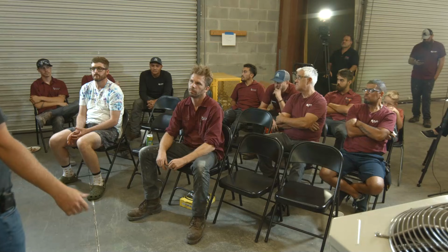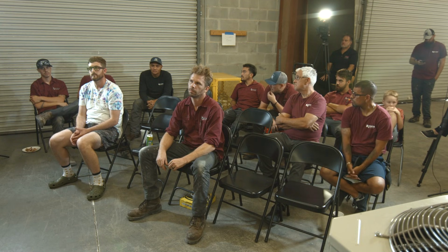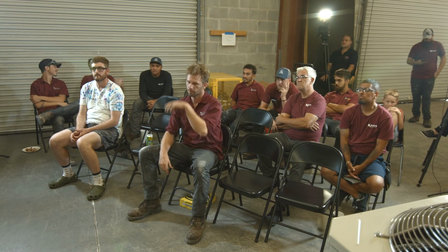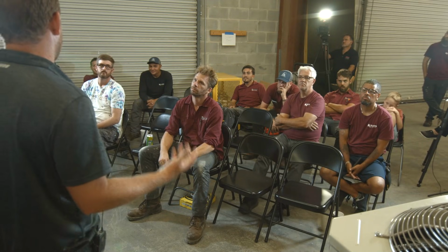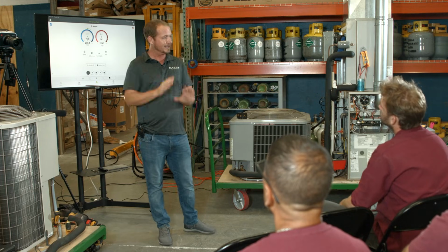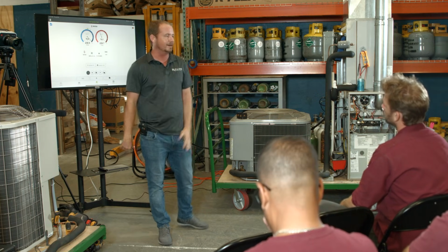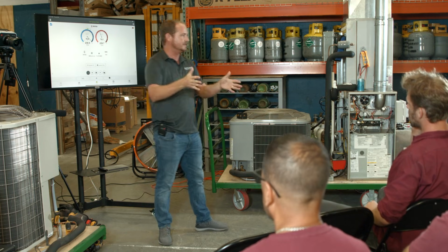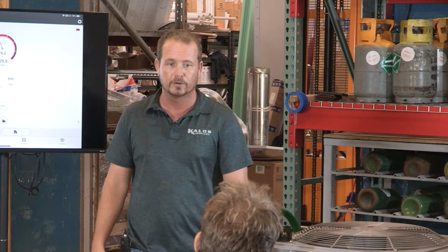You put that little cookie tray thing in the filter that you were talking about. Yes, that's the True Flow Grid. That's probably the best way, the most consistent way. You could do it with a large flow hood on the return. You could do it with a hot wire anemometer in the duct and do a traverse, do a log Chebyshev traverse and lay it all out with your different holes and measure it and take the time average, and then calculate your velocity and then multiply that times the internal dimension of the duct, right? You could do that. Are you ever going to do that?